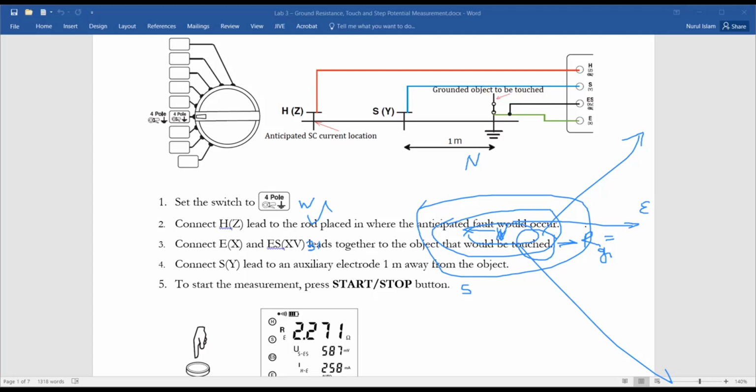And it is because if both of your feet will be on the equipotential line, then you won't have any step potential. But if you stand putting your feet in between two equipotential lines, definitely then you will have some step potential, and because of that step potential, you will have current flow through your body. Okay.